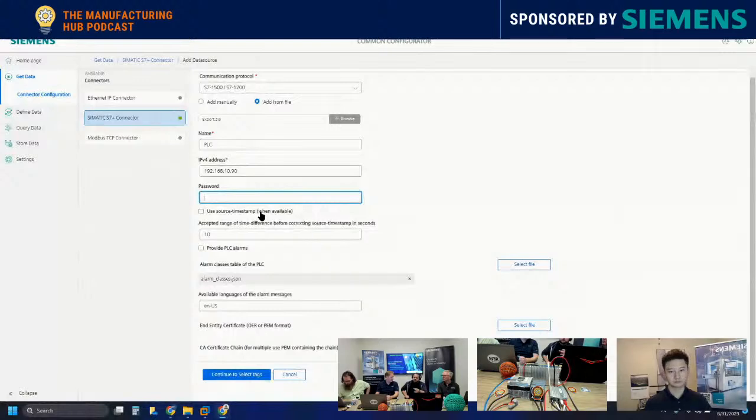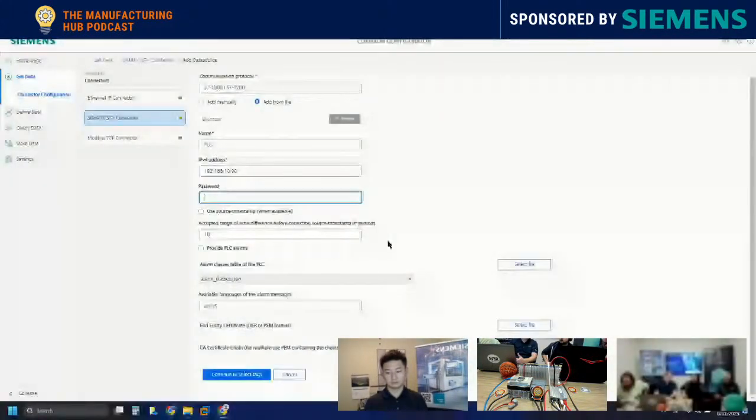So when you pull data, can you specify, I want to pull data on change, or on a time interval, or when it's timestamped by the PLC, like what does that resolution look like? So the way the edge device works, to try and be very lightweight on the communication, is that it is going to be cyclic on change.